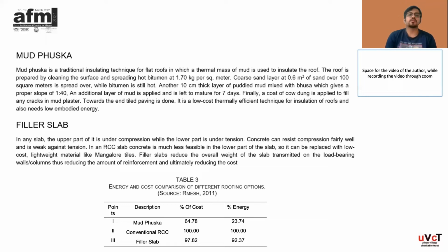The next one is filler slab. In any slab, the upper part of the slab is under compression while the lower part is under tension. Concrete can resist compression fairly well and is weak against tension. In an RCC slab, concrete is much less useful in the lower part of the slab, so it can be replaced with low-cost, lightweight material like manmade tiles.